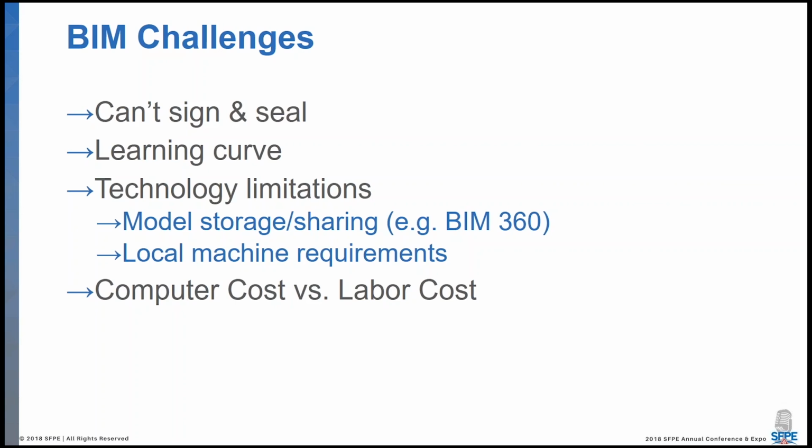The technology limitations. Now, you can run Revit on an entry-level PC with a single core processor with 4 gigabytes of RAM, 5 gig hard drive that runs off platters, and a single monitor. I don't recommend that. Your team might rebel against you if you choose to go that route. We use 16-core Intel chips, at least 16 gigabytes of RAM, usually more, 256 gig solid-state hard drives for very fast upload-download of information, video adapters with shader model 5, multiple monitors, et cetera, et cetera.